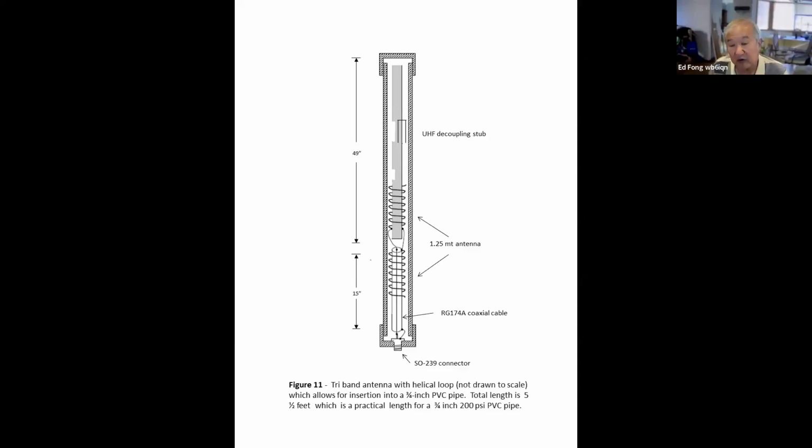And when you tune these things, what I tell folks is you don't have to tune them up at your antenna side. You can bring down the antenna. What's really important is the coax. Try to use the same coax type and coax length because that's what affects the SWR. As long as your antenna is semi in the clear, you're fine. But try to use the same length and type of coax when you're tuning it.